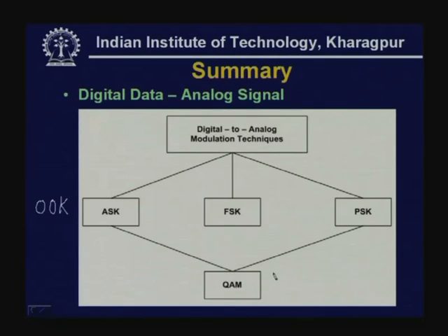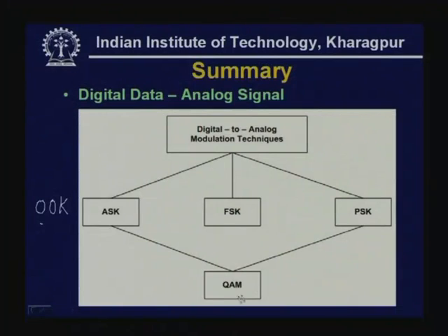On the other hand, the FSK and PSK bandwidth requirements are higher compared to ASK signal, and we have seen how PSK and ASK can be combined to have higher baud rate for transmission of high speed data through the modem. And we have seen there that by using lower bandwidth channel, you can send data at a higher speed. So, with this we conclude our lecture.